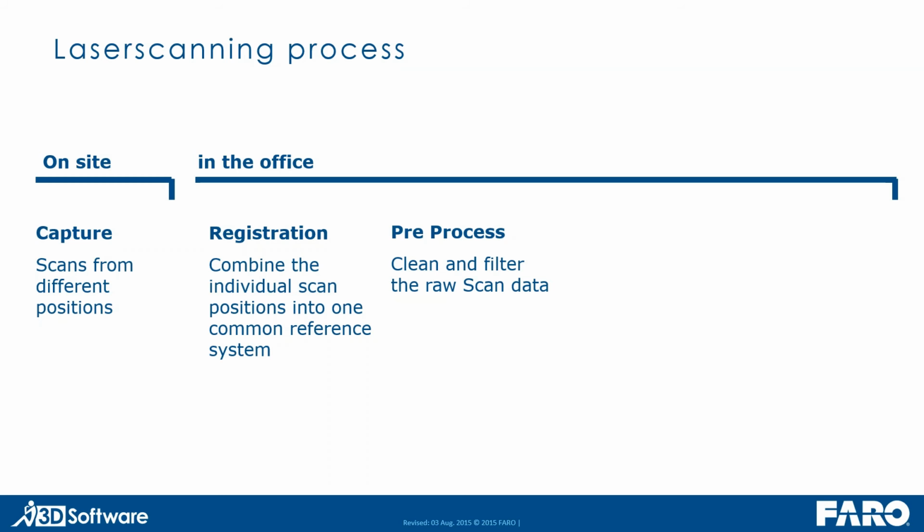And then later in the office you will do the registration and combine the individual scan positions into one common reference system. And you will also do some pre-processing like cleaning and filtering the raw scan data and also coloring.